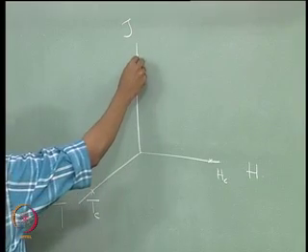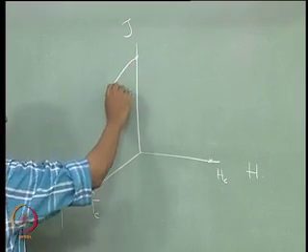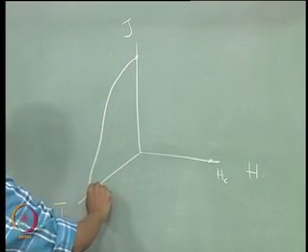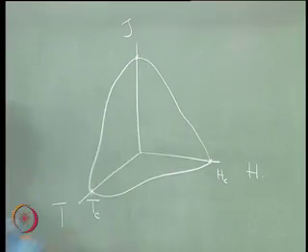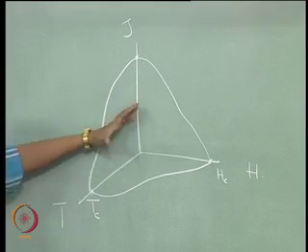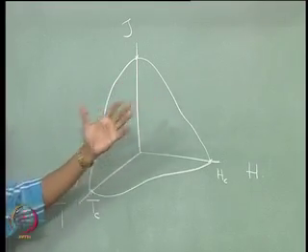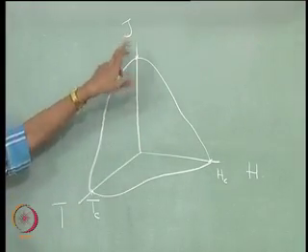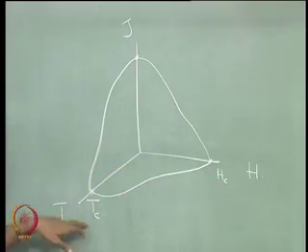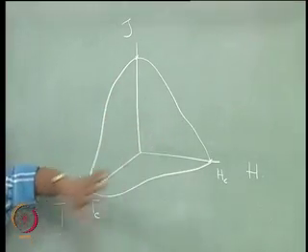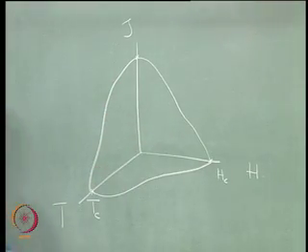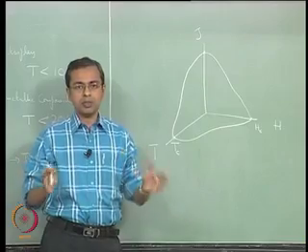So what is actually seen is you have a range of combinations of all these. From the origin till you reach the boundary, there is some surface that you can think of which consists of current density values, field values, and temperature values. Within that surface, as you go below it towards the origin, you have a range of combinations of conditions under which the material continues to remain superconducting, okay.